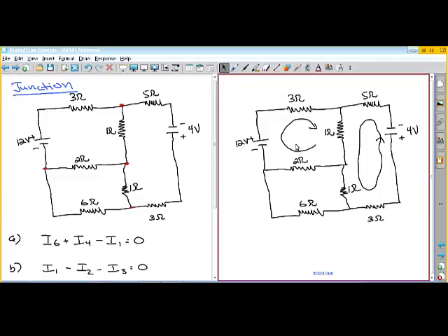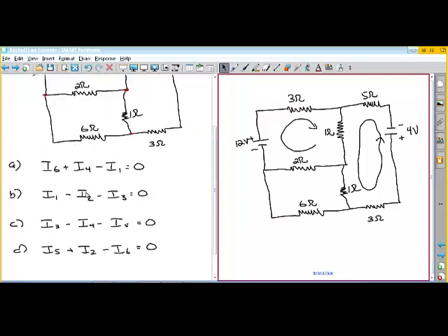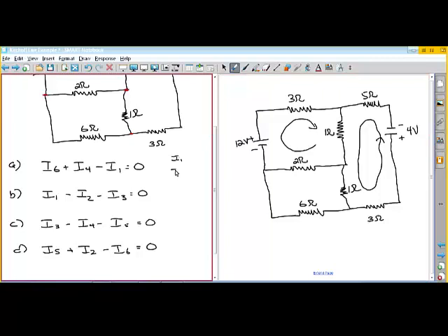Okay, well, I've just been in the book, and it says, apply the junction rule to any junction in the circuit. The rule may be applied as many times as a new current, one not used in a previously found equation, appears in the resulting equation. So that's why it seemed like I had used too many here, because you can see, let's just list the currents. So we have 6 currents. I'm going to list these down, and then we'll mark them off as we use them in equations.